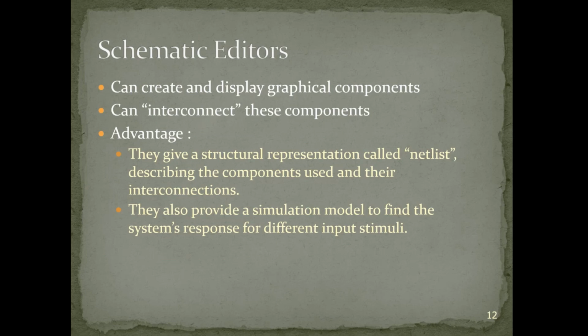Essentially, what we do end up with would be a structural representation. So the structure of that schematic, which would be called a netlist, and that netlist will tell us how the various components used are interconnected to each other, which pin connects to what, how they connect to various ports, and all that sort of thing.